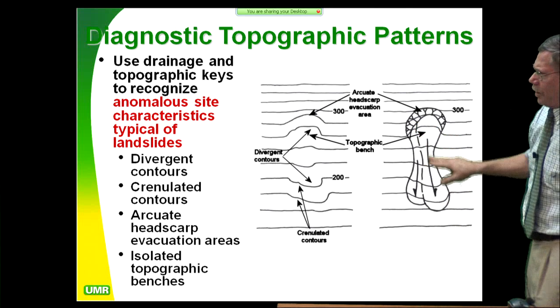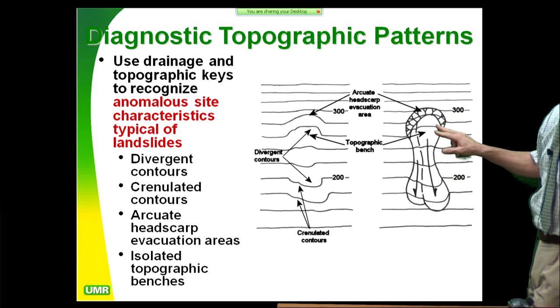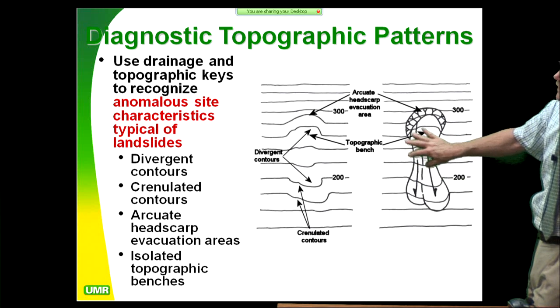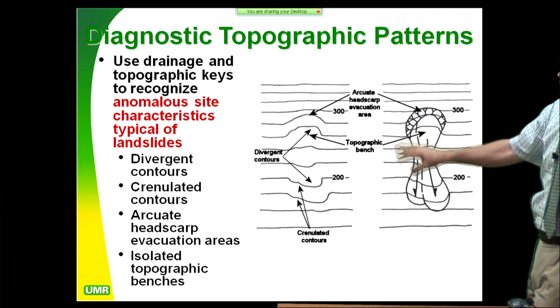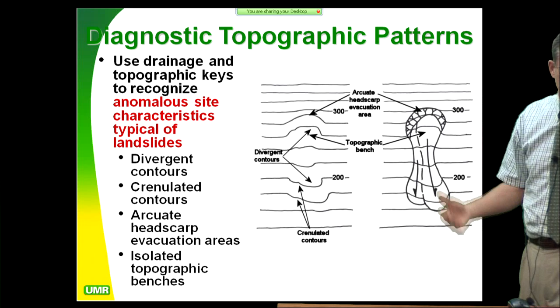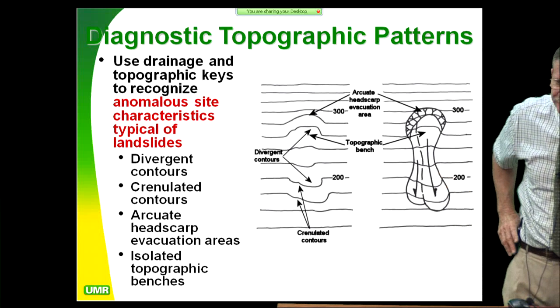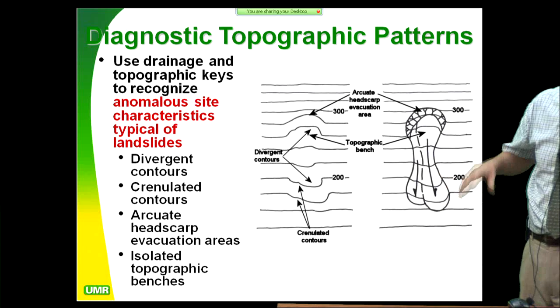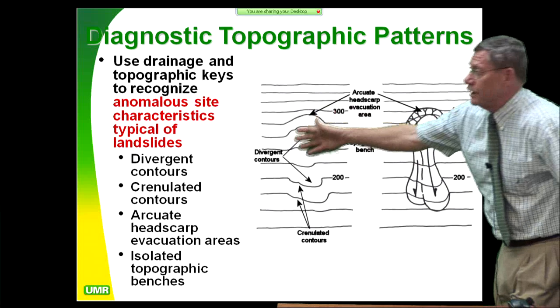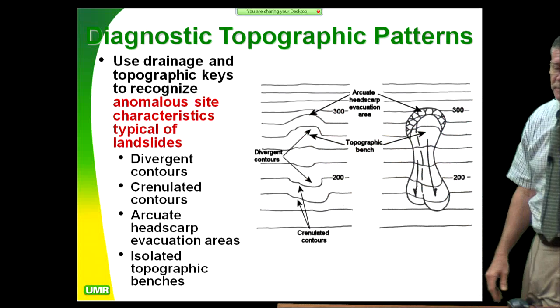Now, you map all this. Does that mean it's a slide? No. It's still subject to your going out there and doing a site-specific reconnaissance to see if there's something else going on. What are some of the other things that can go on out there that I haven't mentioned? Use your head. Use your imagination, boys. I mean, somebody could have been out here doing something. There are other things people could be doing.